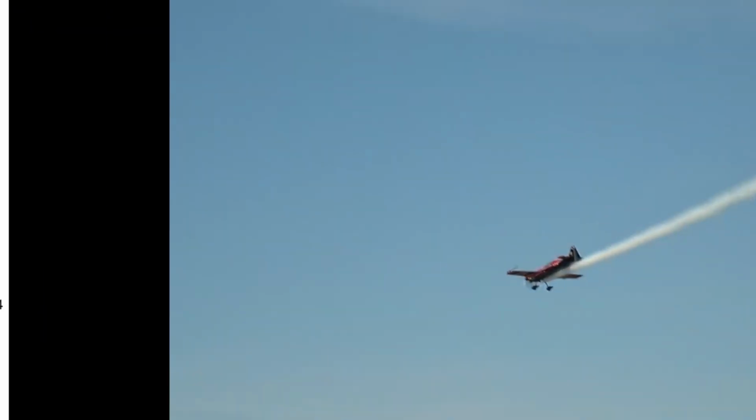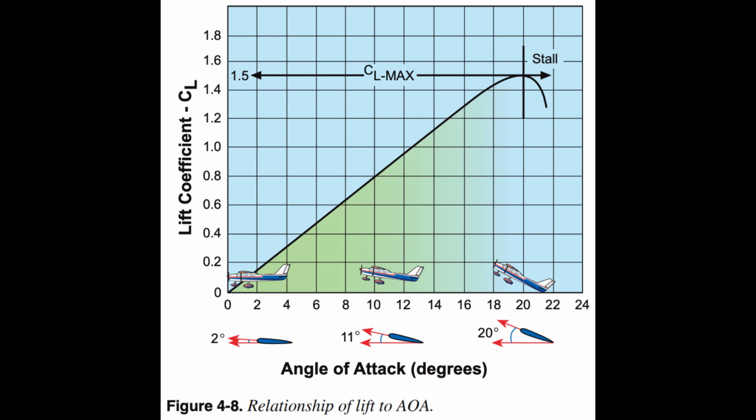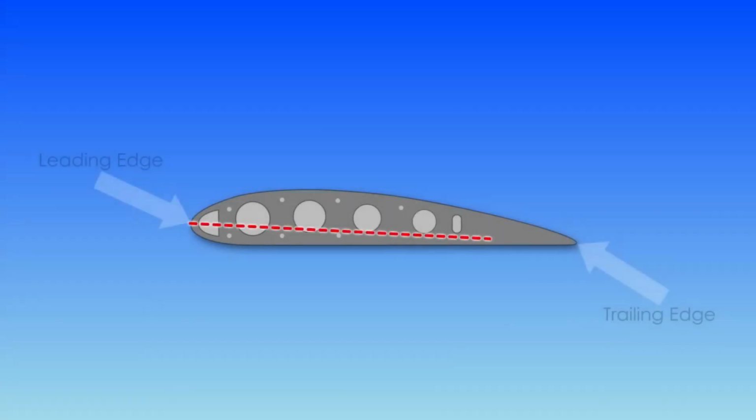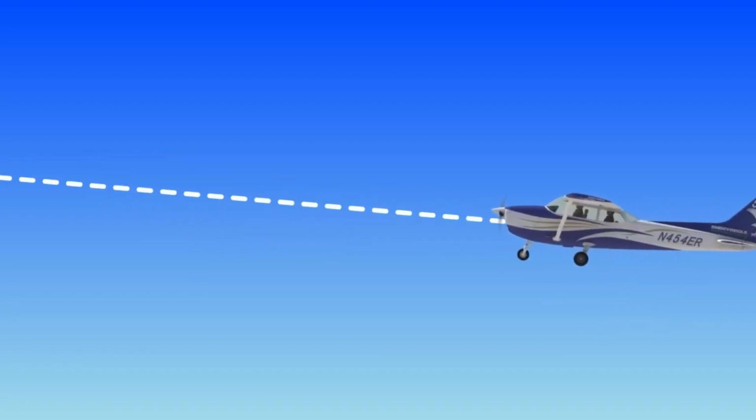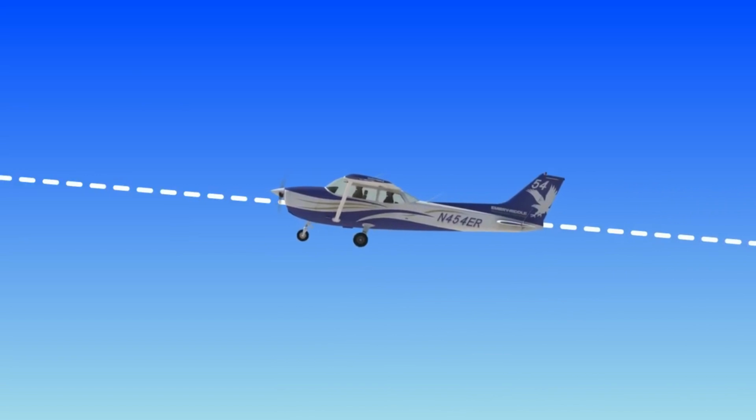Pitch/power relationship. An examination of Figure 4.8 illustrates the relationship between pitch and power while controlling flight path and airspeed. In order to maintain a constant lift, as airspeed is reduced, pitch must be increased. The pilot controls pitch through the elevators, which control the AOA. When back pressure is applied on the elevator control, the tail lowers and the nose rises, thus increasing the wing's AOA and lift. Under most conditions, the elevator is placing downward pressure on the tail.